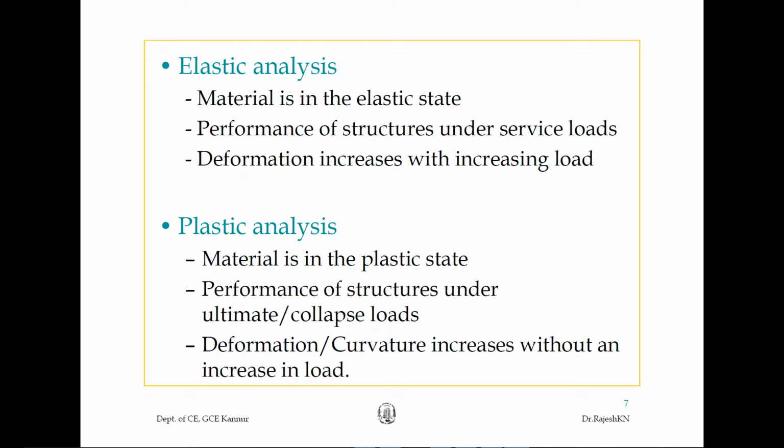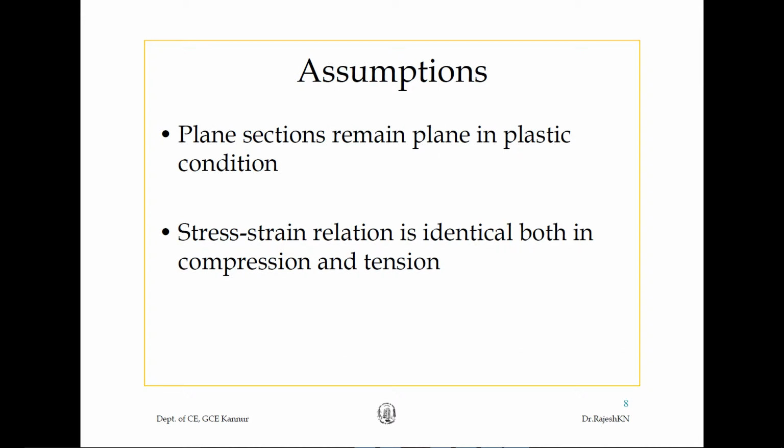In plastic analysis, the material is in the plastic state. The performance of the structure is under collapse load, meaning we are going to the ultimate collapse load. And deformation increases without an increase in load. As we have seen, without increasing the stress value, strain is increasing.